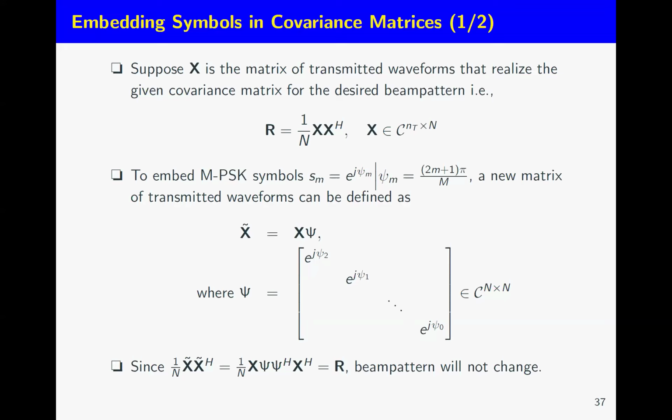From your experience, what are the expected figures for main lobe jamming suppression and side lobe jamming rejection in comparison with traditional radars, especially those equipped with ultra low side lobe antennas? I have dealt with these ultra low side lobe antennas. The side lobe level was about minus 50 dBc. Thank you.